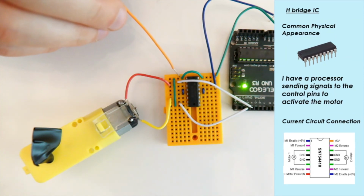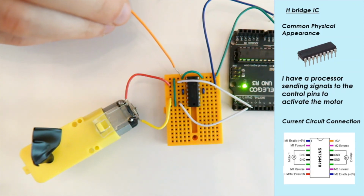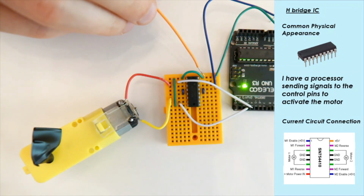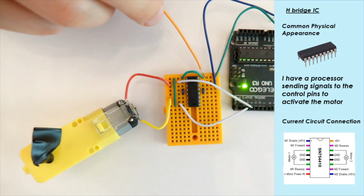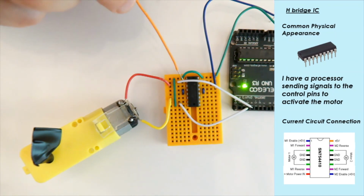Our first pin, pin 1, is our motor 1 enable pin, which needs to have 5 volts sent to it to turn the motor on. We've decided to use this green wire along to pin 16, which also needs to be 5 volts for the logic. And we've hopped it along this green wire to our processor, which is outputting 5 volts along this green wire, which is then shared across here and further down as well, but we'll get to that.